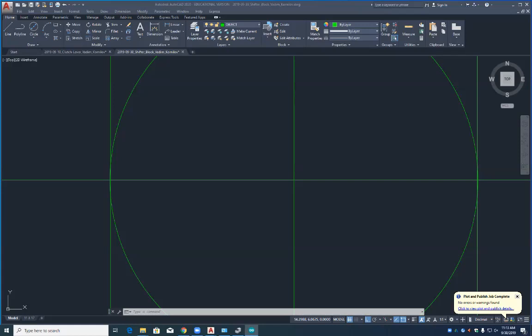Just pick a point. Okay. @ 0.005, shift less than 0, enter. That's all you do. So with the @ command, you can move. You can copy using the @ command. It's not just drawing lines. You can copy and project it in different angles and distances. Exactly.